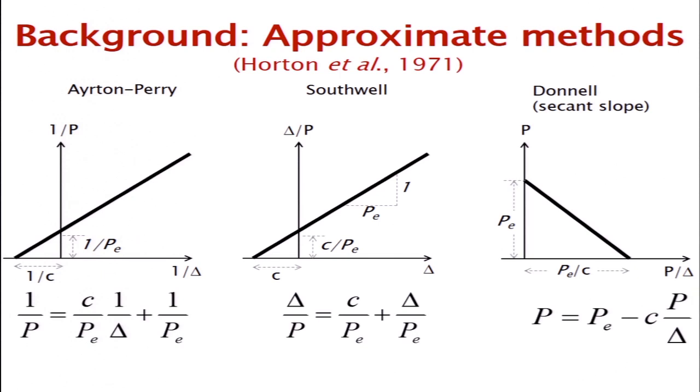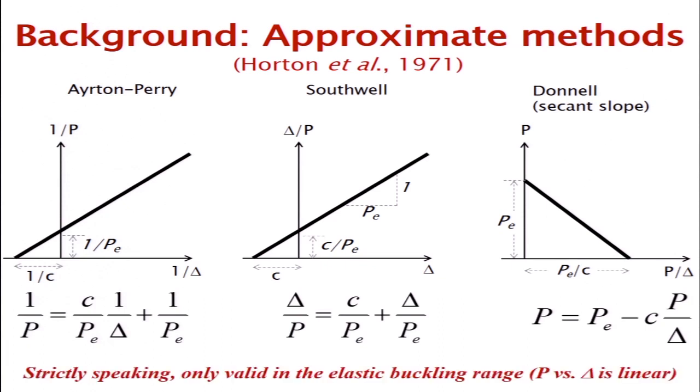And what you do is, if you, for example, had a couple of points or several points along the loading, you can take those, linearize, and extrapolate to what the buckling load would be, which is what we are doing. Okay? And so we don't have to get to the buckling load. We can extrapolate, or at least we think we can.